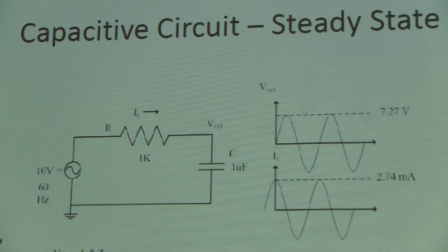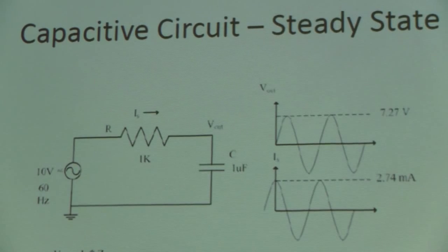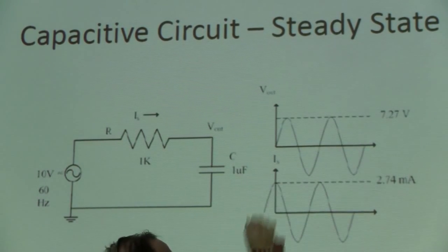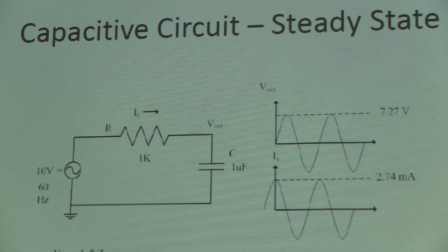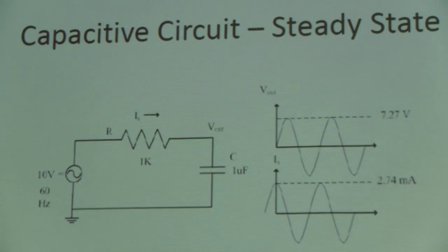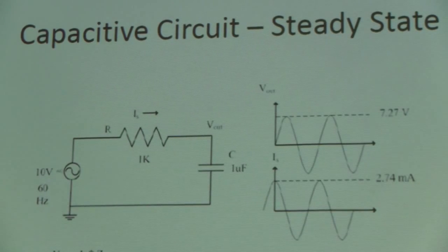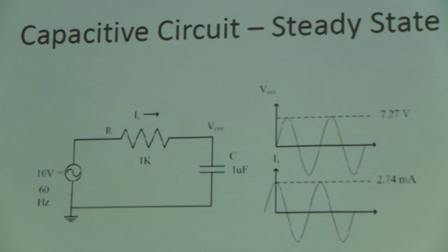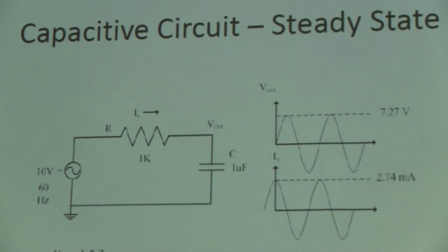Otherwise, once I know it's capacitive, and I've addressed the issue that there's a phase difference, it starts to look again like a resistive problem. That is, if I forget about the phase for just a minute, I look at the impedance of this capacitor, I take its magnitude, which, since it's a phasor, you get the magnitude of a phasor, it's just each component squared, summed, and then square root.